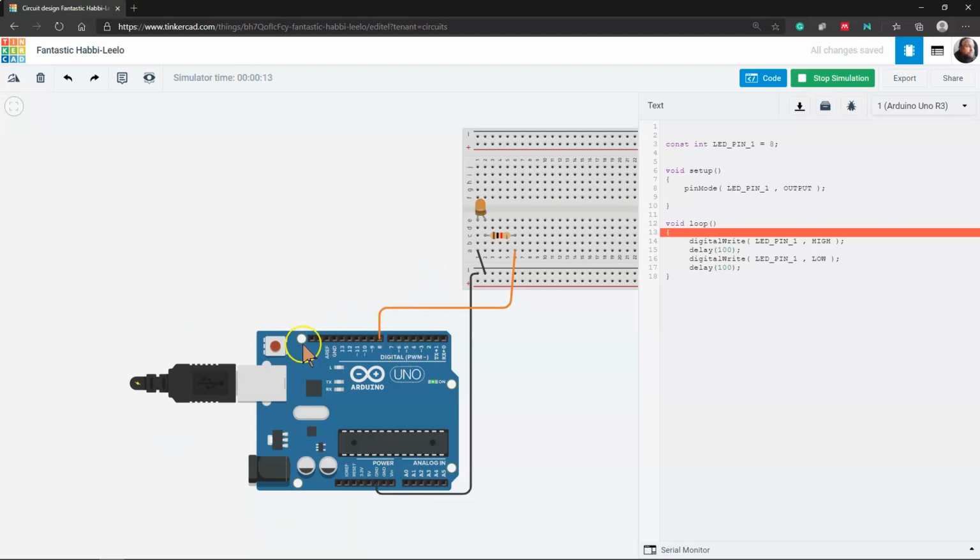So again, the idea is that we have our one circuit. The Arduino allows for multiple circuits to be connected to this. You have your ground that's coming back to complete it, and we have this one individual circuit for just controlling this LED. We can have another LED thrown in here if we want to do other work and start working with two LEDs and building stuff up. We build another circuit, we hook ground to it, but then for the start of the power, we have another pin to control it.